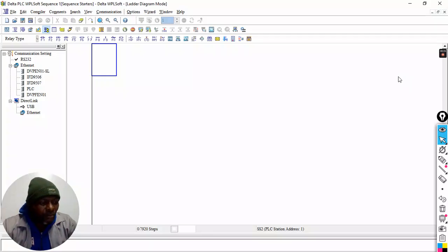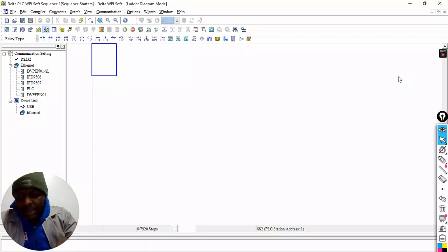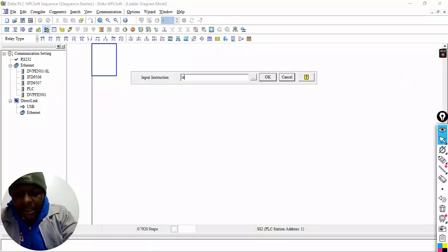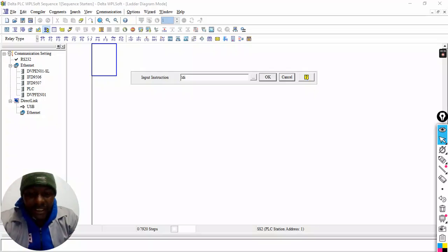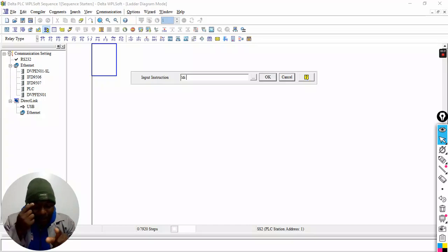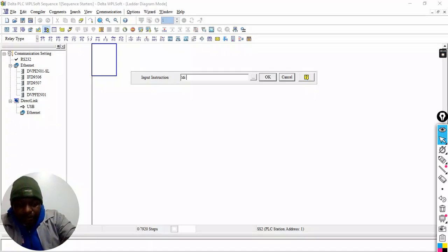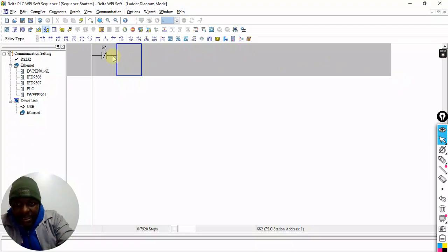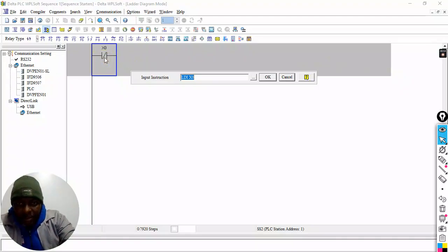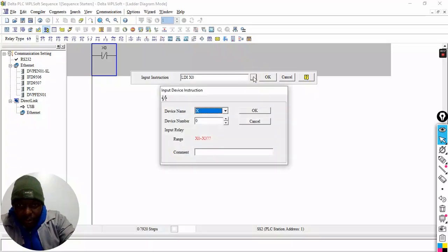And then so let's go with this. Now we are going to say we have one emergency stop. So what I'm going to do is load an emergency stop here. It's a normally closed, even though in reality it's going to be what? Remember, emergency stop is a normally closed already. So in reality it's going to be normally open, but for purposes of simulation here and for theory purposes, we're going to keep it as normally closed. That will be, let's say, x0. Emergency stop for both, because we said we're going to use one emergency stop, which is possible. That one's not an issue.